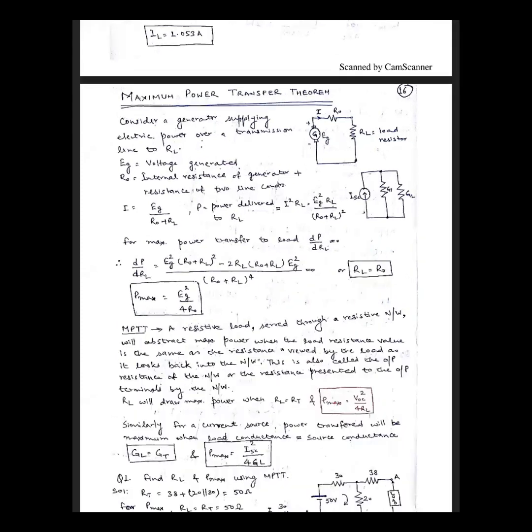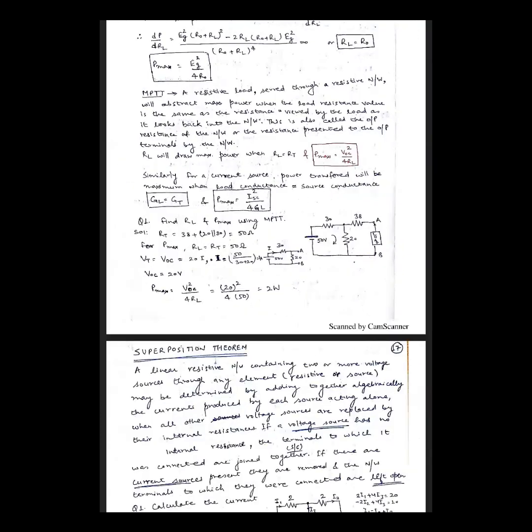So we can now conclude in this theorem that the power transferred is equal to this. If the circuit is simple, then we can go for EG, the generator EMF, and if the circuit is complicated, where series and parallel combinations are required, then the voltage is replaced by the open circuit voltage, because we are already calculating the Thevenin resistance also.